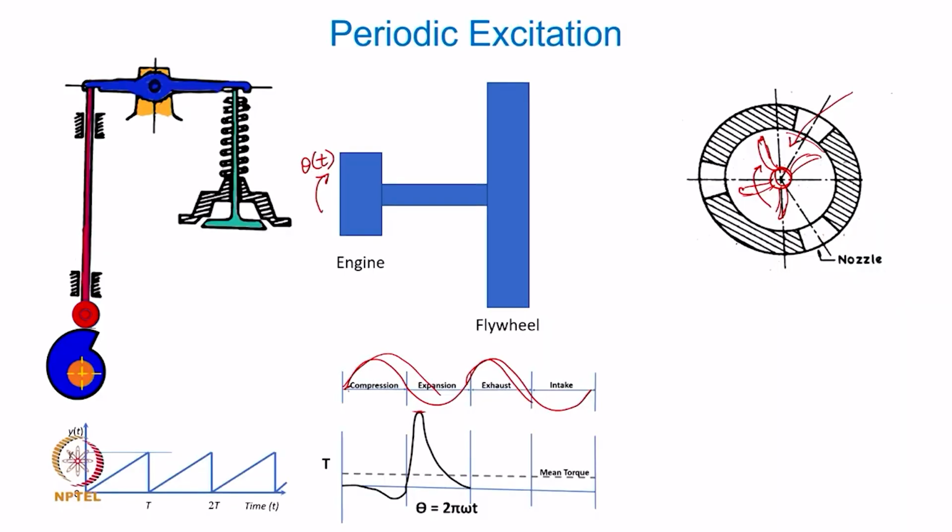In this case, you see that there are 3 nozzles, equiangularly situated. So, if I consider a blade to be a vibratory system, then this force as a function of time again is no more a harmonic force, isn't it?